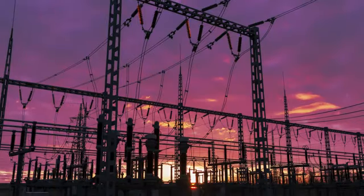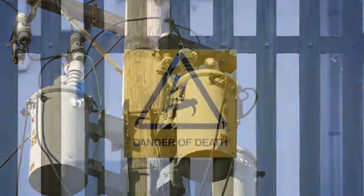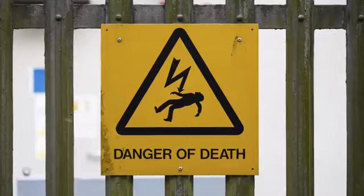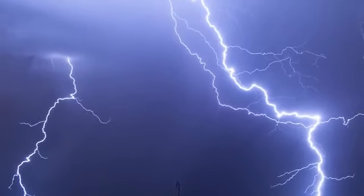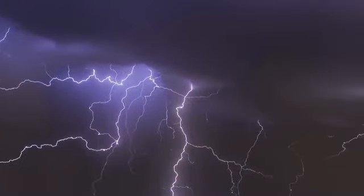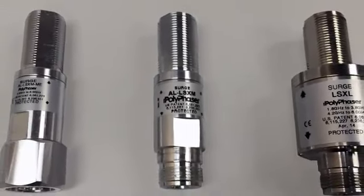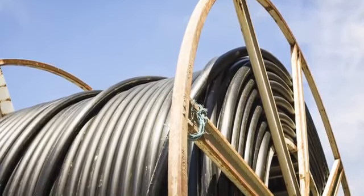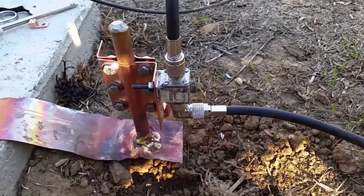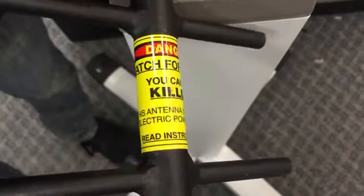Not only do you want to stay away from sources of electrical noise, such as power lines, electrical motors, solenoids, high power radio sources, or any high voltage power usage in order to improve signal reception, but you want to avoid the possibility of electrical shock, which can be fatal. Speaking of which, another important consideration when installing an antenna outdoors is to have proper lightning protection. Placing an antenna high above the surrounding terrain may give you great signal coverage, but it also makes it vulnerable to lightning strikes. Using a coaxial lightning arrestor with a grounding wire for each antenna can protect your radio equipment from serious damage. The grounding wire must be of the proper gauge as per the manufacturer's recommendation, and it must actually run to ground. Installing antennas can be a hazardous affair, so be sure to follow all safety warnings on your antennas and other radio equipment.